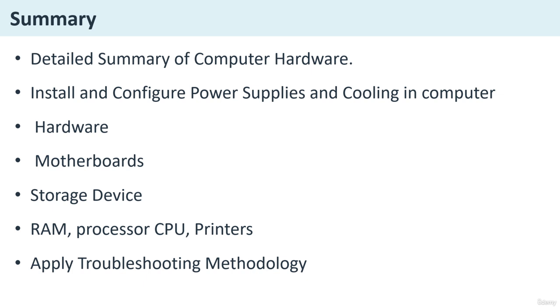I will also tell you about motherboard troubleshooting. First of all, sometimes there will be no power. For that, please check the PSU and front panel connectors. Number two, where there is no display, ensure GPU and RAM are seated properly in their slots. Number three, sometimes a USB port is not working. That means update the driver or check the BIOS settings. A good motherboard ensures all components work together efficiently.